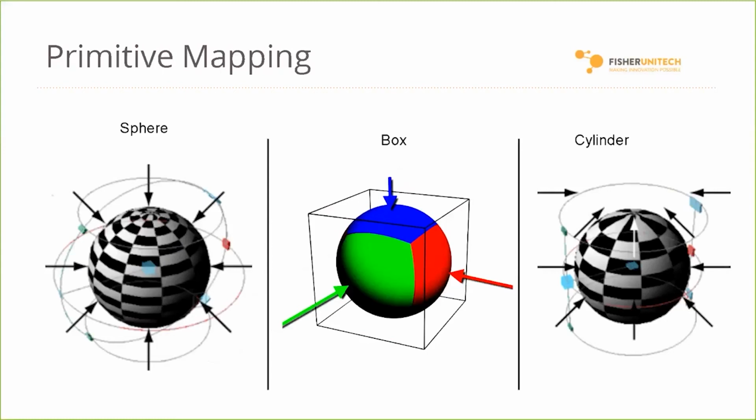We're going to use the example of a sphere here because you can see each one of these pitfalls for a complex curvature object. So in box mode, obviously it's going to be good for boxy objects. Cylinder mode is going to be great for a cylindrical object. You can see here on this sphere, though, that we still have that skewing on the top. So a lot of times you can pick some of these primitive mapping modes to fit onto a geometry, and it's very fast. It's a very quick way to do the UV mapping.